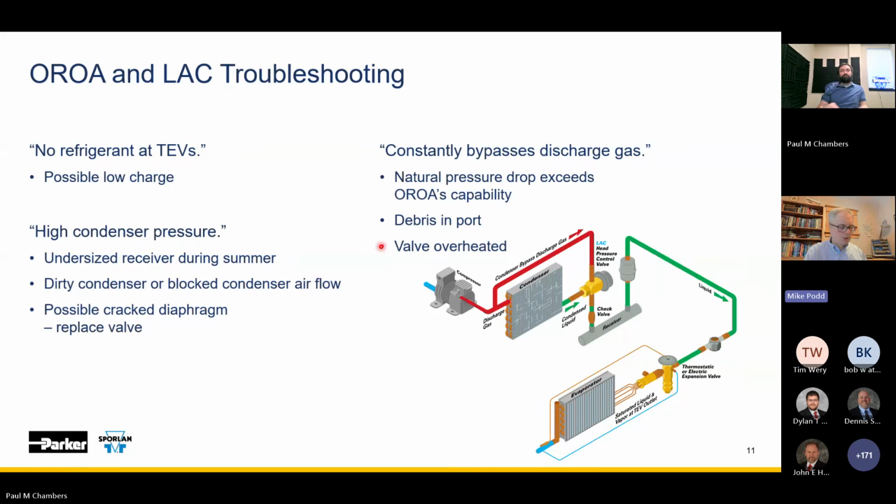And another point is if you've got a system that has a bad condenser fan, especially a single fan condenser, and it's going off and on and off and on, the diaphragm in this valve is going to be up and down and up and down. As those pressures deviate, you'll prematurely wear out the head pressure control. So catching those things, addressing those problems, head pressure control fluctuations, things that aren't working can cause system pressure fluctuations. Those can lead to diminishing the life of not only this valve, but the other bellows style as well.